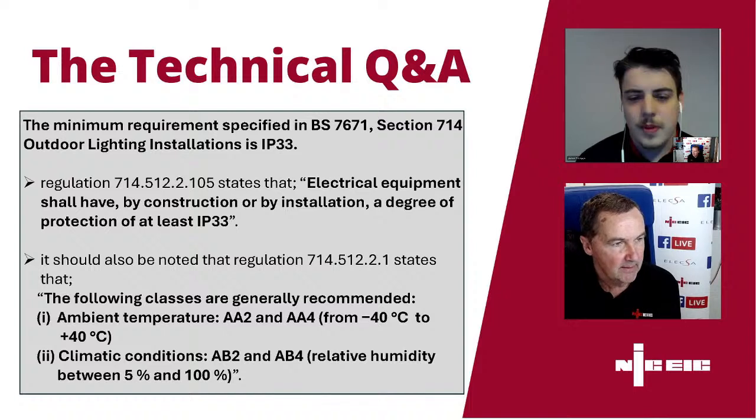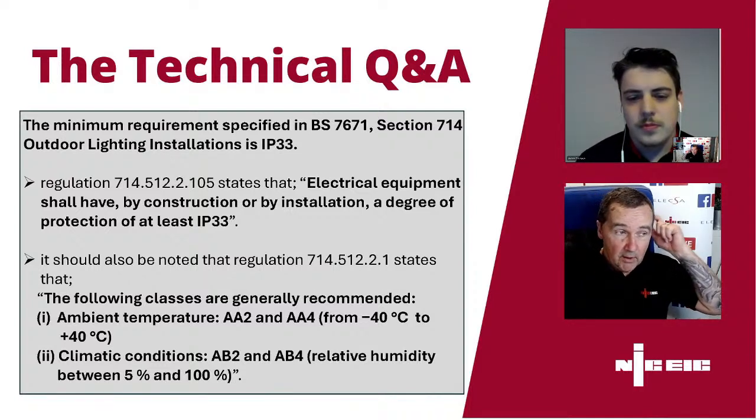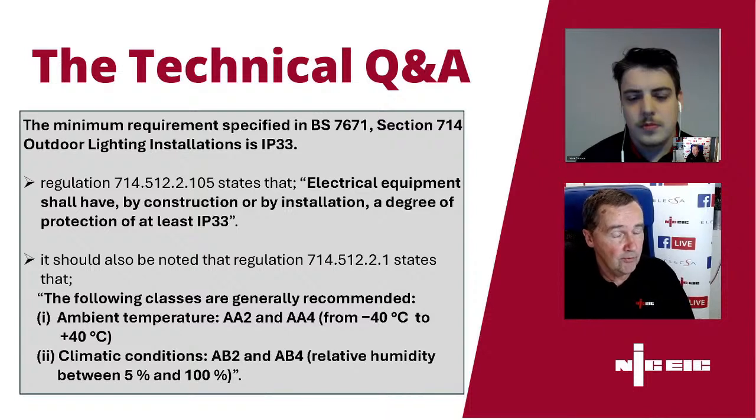Obviously some of the older parts of the installation which weren't modified or altered would be in an older state. It's quite clear that the certificate will only cover the work you've done, and therefore the recommendation for the next inspection is only applicable to the work you've done.